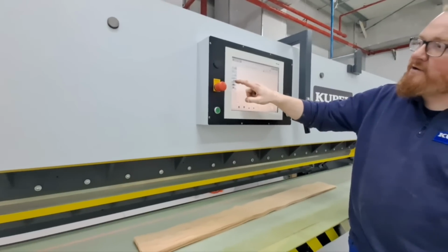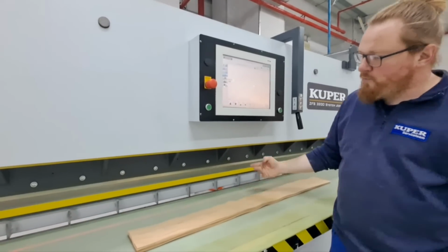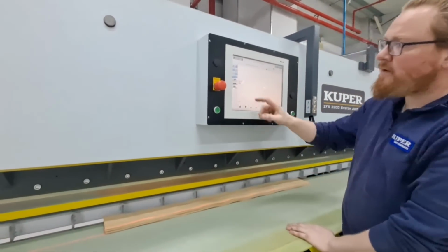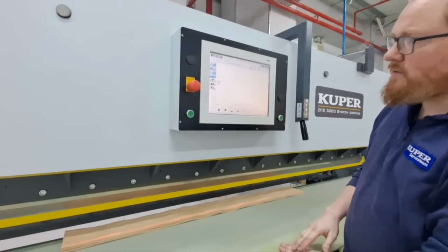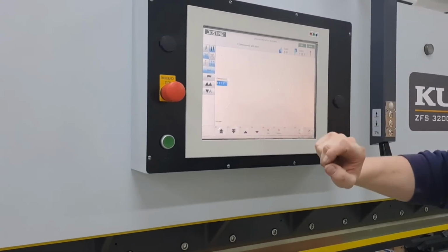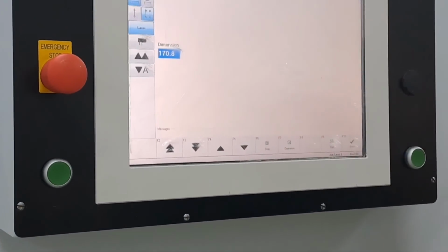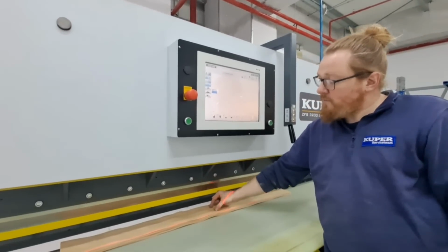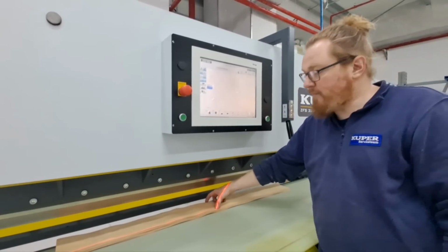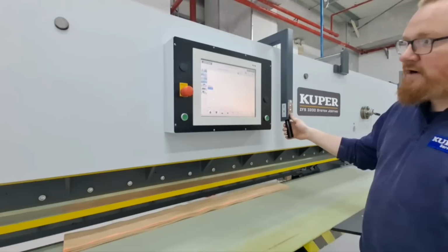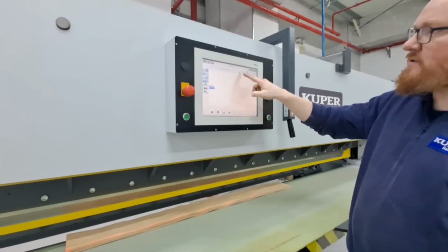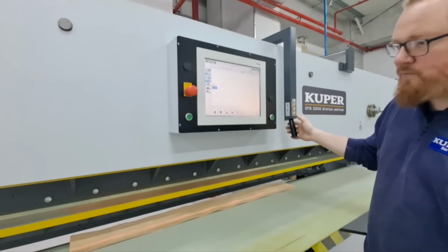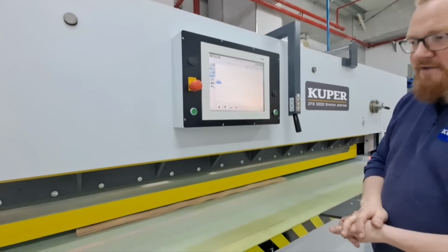The thing is that we have the stopper here. When we bring that up, we can adjust the veneer a little bit easier, and we can bring it down manually. Choose dimension with laser. Then I can have a look at what the maximum of the veneer is, so we can see where the good quality is and where the bad quality starts. And when we then start, it will measure with the laser, and the table will go to the same position. So I cut off a little bit more, and then you will see our double cut is working.